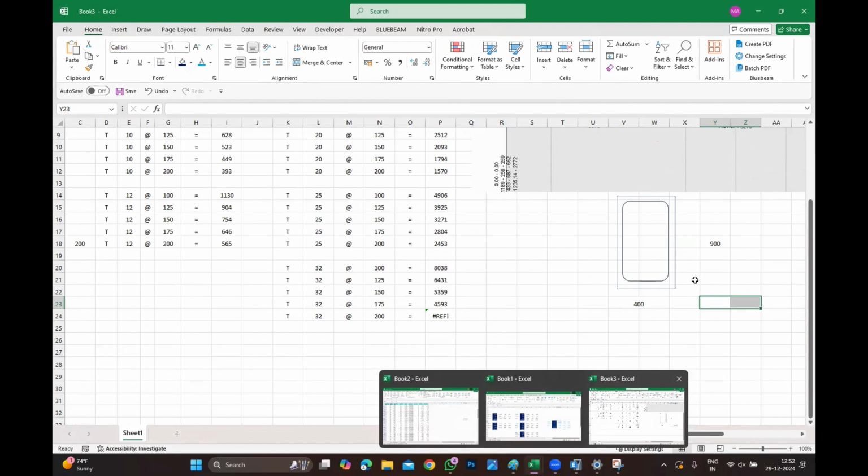Because you need the clearance between the rebars at least minimum 60 millimeters to put your vibrator. There are two vibrators, right? 40 and 60, isn't it? Needle, right? 25 also is there. But are you using 25 in beams? So in general, you're using 40, right? If you want to use 40, at least minimum 50 is required. 50 to 60, isn't it? So consider the minimum bar spacing required as 60.